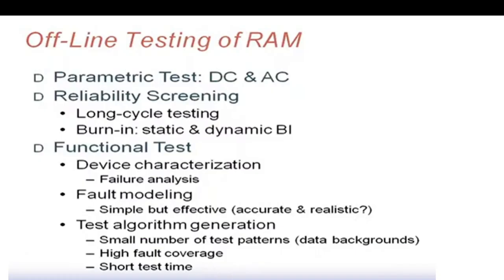Next, offline testing of RAM. So it can be a parametric test of AC and DC, reliability screening, long cycle testing, burn-in, either static or dynamic burn-in. Functional test, which includes the device characterization, failure analysis.